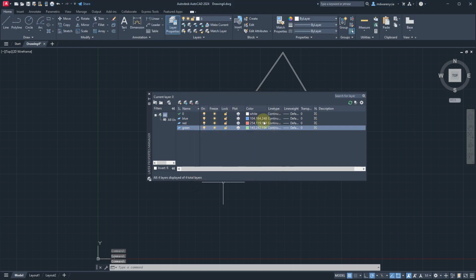Why would you want to do this? It helps organize your layers, and we'll get into that once we have a floor plan we're working with next class. But you end up with a whole bunch of stuff in this drawing, right? This is the way that we should be working with AutoCAD: you should have a floor plan and just one floor plan. And then everything that's in there, your dimensions, your room labels, your furniture, your electrical labeling, your plumbing, all that, everything's going to be on top of itself. And so what you would do is organize things on different layers. So then, and we can actually close this now.